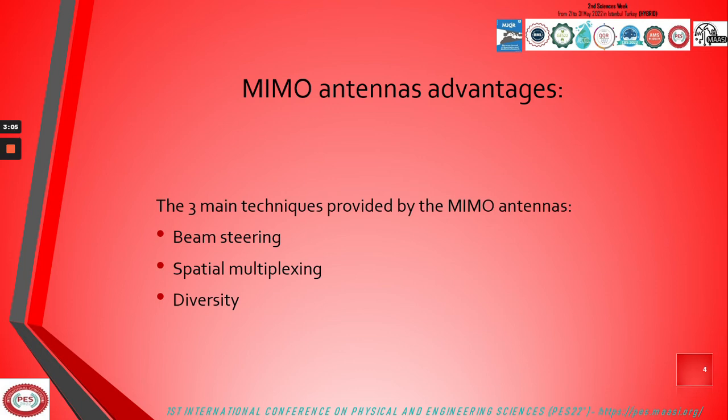Next, we have spatial multiplexing. This technique adds data carrying on the same bandwidth, which increases the data rate according to the Shannon-Hartley theorem. At last, we have diversity. Diversity is a method that allows each signal to be encoded properly. The aim of this is to permit each signal to adapt to each channel by compensating losses and adding noises, meanwhile adding redundancy that will correct bit errors, which guarantees a crucial requirement for the fifth generation.